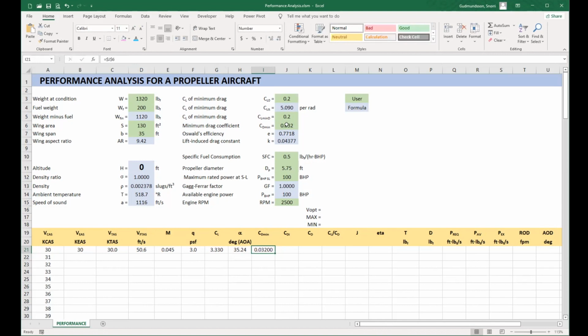What we are doing here is to really assume the CD min represents an average, which is why there will be a constant value for all airspeeds. Anywho, here we refer to the CD min entered earlier, 320 drag counts. Next, calculate the lift-induced drag. For this, use equation 15-6 or 16-88.